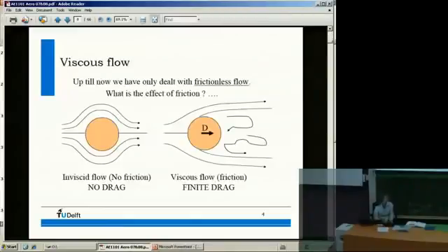So viscous flows, what are they? Well, a viscous flow has a quite different topology than inviscid flow. Suppose we put a cylinder inside an inviscid flow. Of course, truly inviscid flows do not exist. There's always a small contribution of viscosity, but suppose, as a thought experiment, what would the flow then do? It would flow perfectly around it, be perfectly symmetrical, attach here again and continue like this. Well, if you've ever put some object in a flow, that is not what happens, right?